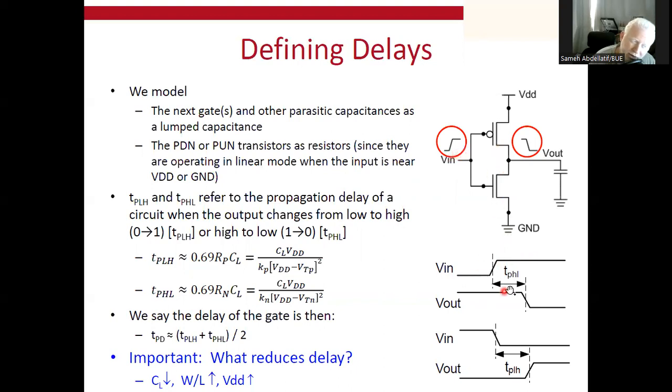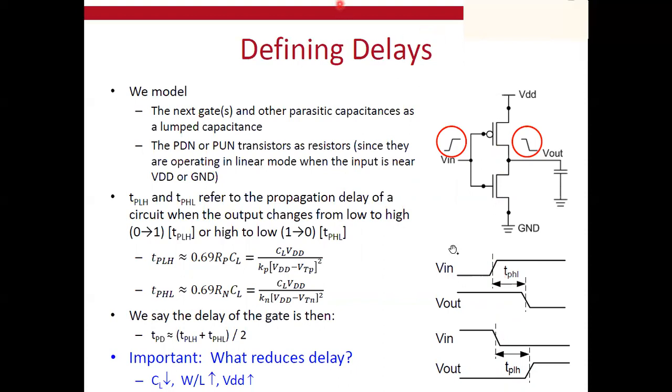So this is an example of how we can consider the delay. Here we can see this charging or discharging time, which we can call the rise time and fall time in an IC chip. This is of course with the clock. If this is a V input and this is a V output, supposedly if we are working in an ideal manner, the V output should be identically equal to the V input, but due to this delay, we start to have a propagation delay, as you can see.